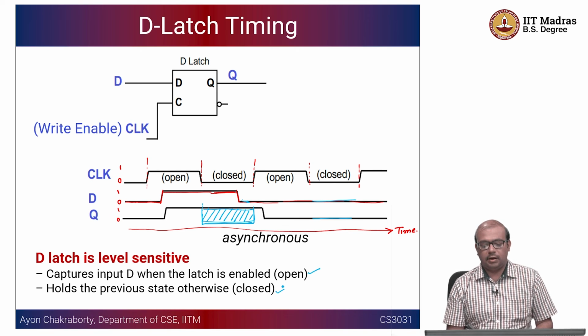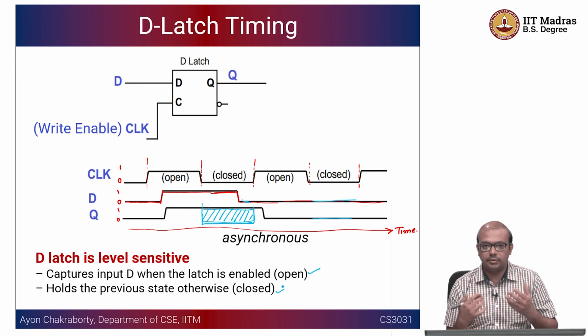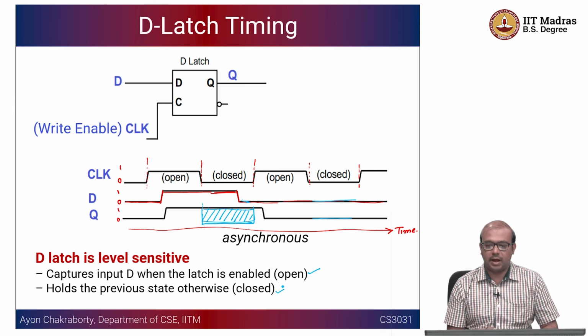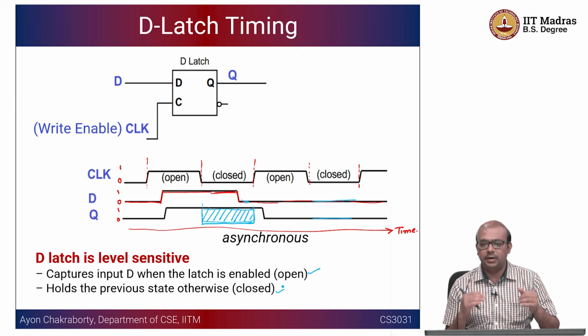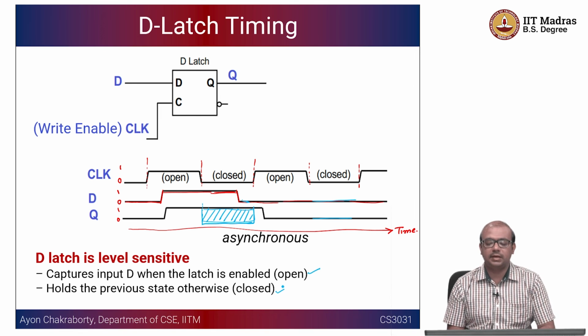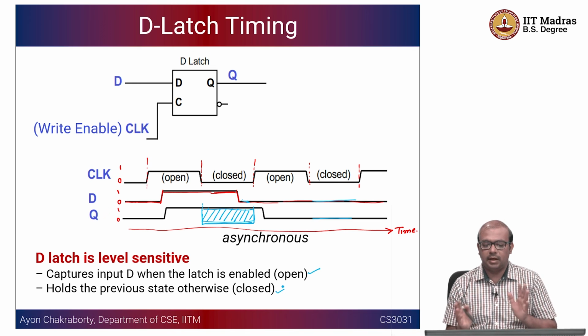Okay, there are many applications that are okay with the D-Latch, but particularly when we are really careful, or when we want to do something across multiple circuits and I need to follow a certain global timeline, in that case this is not very good, because these times could be fluctuating because of various reasons.